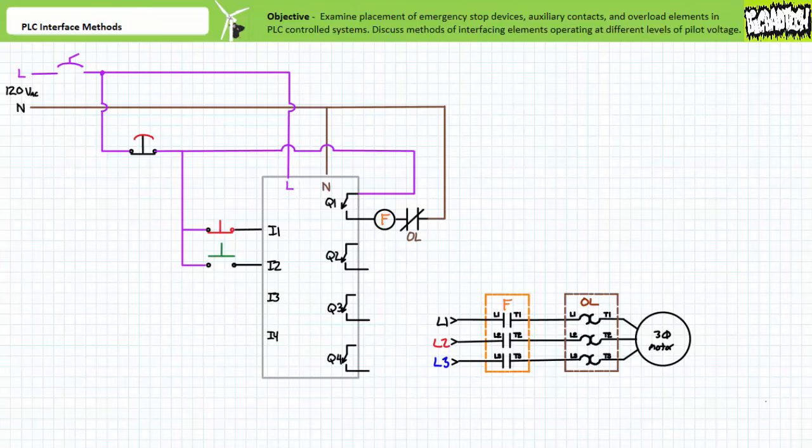If the PLC controlled system continued to energize output Q1, and if the overload was in automatic reset mode, the moment the overload cooled, the motor would turn on again, and if the condition persisted, would overload again. A very simple solution to this scenario is the incorporation of the F1 auxiliary contact as an additional input to the PLC-controlled system. Recall that contactors, in addition to a coil and primary contacts, often include accessory pilot-level auxiliary contacts